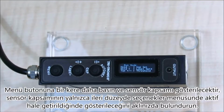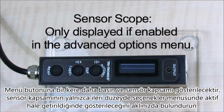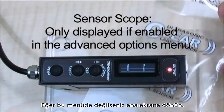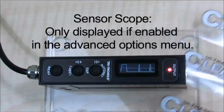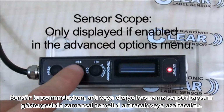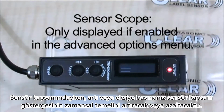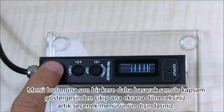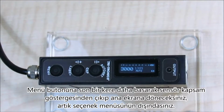Tap the menu button once more and the sensor scope will be displayed. Note that the scope will only be displayed if it has been enabled in the Advanced Options menu. If not, you will exit the menu and return to the main screen. While in the sensor scope, tapping the plus or minus buttons will increase or decrease the time base of the sensor scope display. Tapping the menu button one last time from the sensor scope display will return you to the main screen. You are now out of the Options menu.